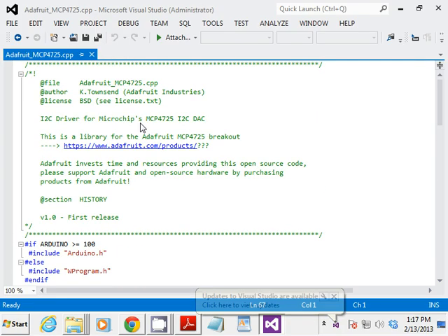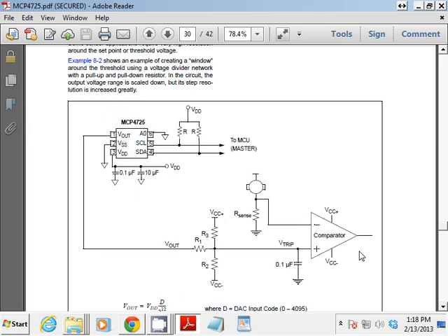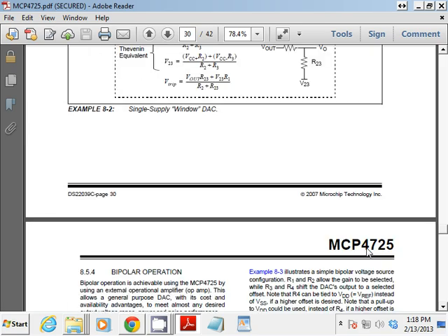That's one of the reasons why I selected it, is because I knew you'd be able to find some canned solution for a microcontroller. Picking a microcontroller peripheral out of the blue without thinking about software is a bad mistake. So when you're shopping for the right A to D converter or D to A converter, it's really good to find out if others have done something before you and borrow the software. Because in general, you're going to have to change the software some, in order to make things work properly.